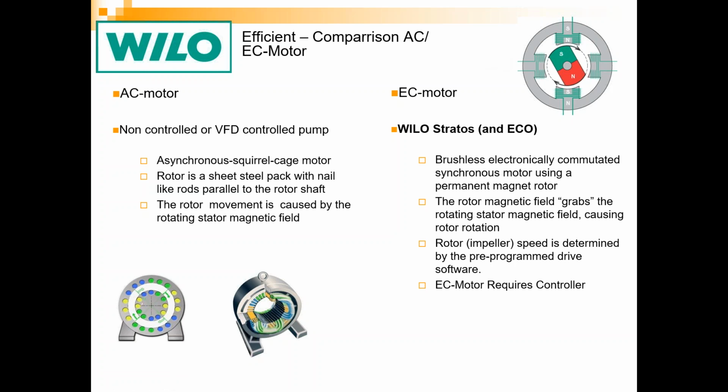And when you have permanent fixed magnets inside of the motor, if you don't pull out ferrous material before it gets into the pump itself, it's going to start pulling all that ferrous material out of your hydronic loop. And it doesn't matter whether it's a chilled water system, or hydronic heating, or condenser water loop, whatever it is, this type of pump will pull magnetic particles.